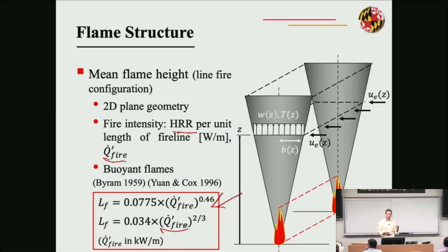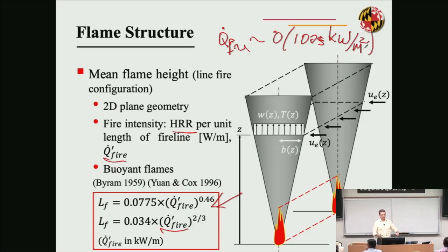So also, what are the typical values of the heat release rate or the fire line intensities in fires? Well, the heat release rate, Q dot fire, for a pool fire configuration is typically going to be on the order of, let's say, a few hundreds kilowatt per meter square. It depends on what you're burning, but a representative value is, if I'm burning this table, I'm going to say, roughly speaking, 100 kilowatt per meter square of table. This is a typical value. Okay, I may be off by a factor that I can make more accurate if I know exactly the composition of the table.